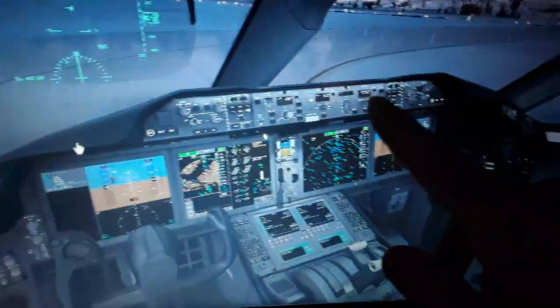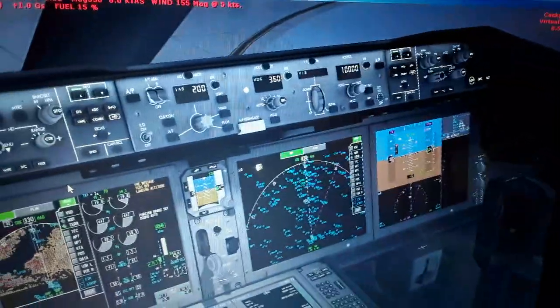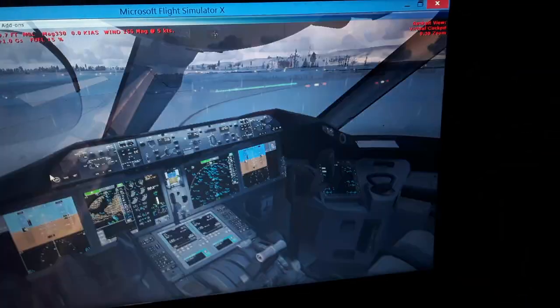So when we are flying manually, or we have the autopilot flight director system panel connected with the LNAV, the VNAV, or the auto throttle or other modes, we have the auto trim function for the horizontal stabilizer over here.